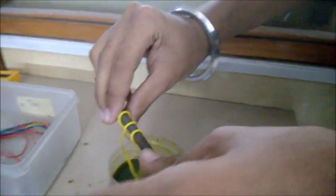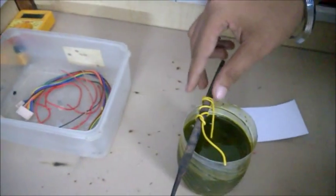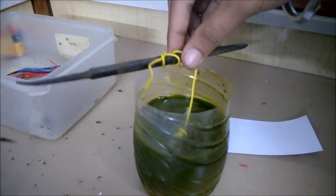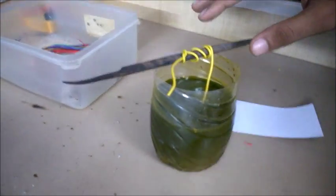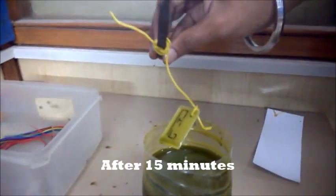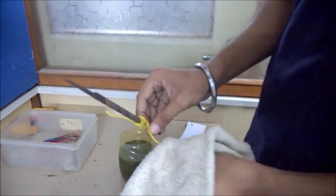Now, the solution's name is FeCl3, and it will take around 15 to 20 minutes for complete etching. After that you can take it out and wash it. I think it's done. Oh yes, it's done. Now we have to clean it. Avoid touching the solution.